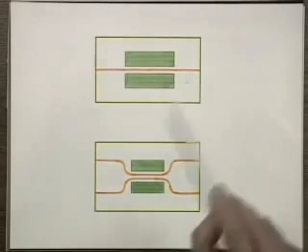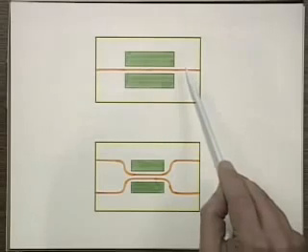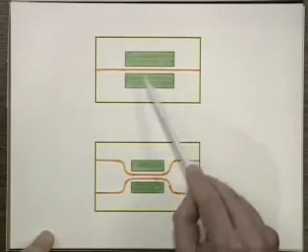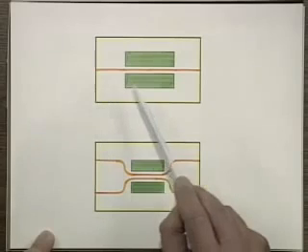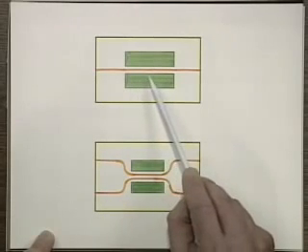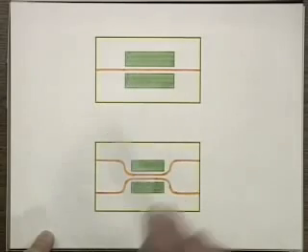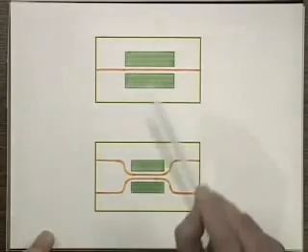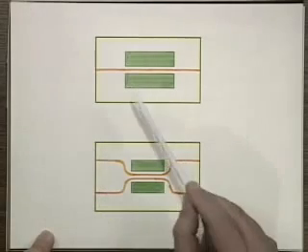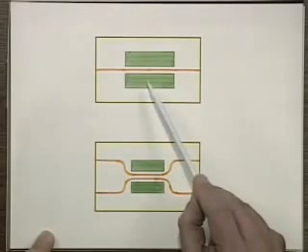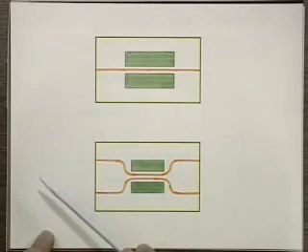All right. So now, how do you create a phase modulator here? If this material is, for example, slightly electro-optic, then by putting electrodes here and applying a voltage difference between them, you can change the index, either in the cladding or in the core, simply by applying a voltage. This way, you can phase modulate the light propagating in this section. You can do it pretty fast, and then you can get very fast phase modulators. And if you ramp the phase using serrodyne techniques that we hear about today, you can also do frequency shifting quite easily using this device.